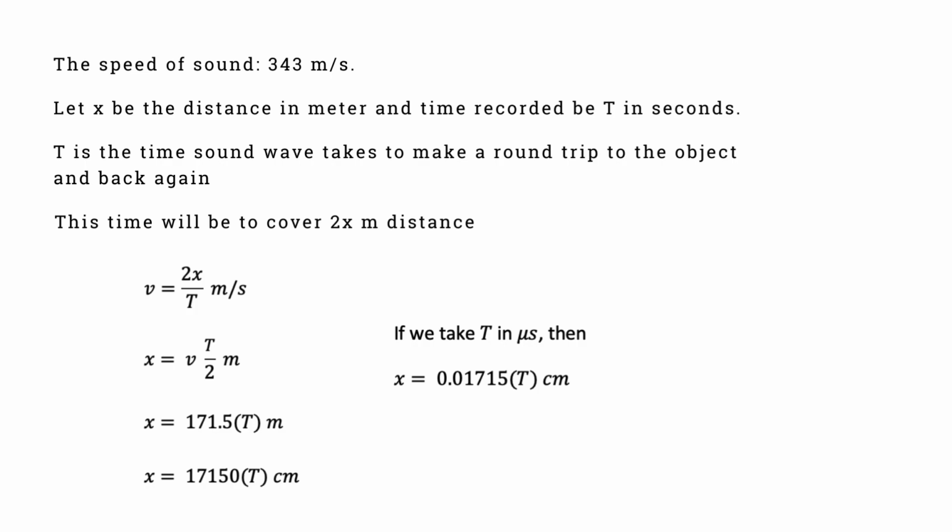Sometimes you may also come across a figure of 58.3 microseconds at various places. Do not get confused, this is the time for a pulse to travel to an object at a distance of 1 centimeter and then return back to the sensor. For that you can invert this value. But never mind, we will be using the above expression of 0.01715 multiplied by the time measured in microseconds.